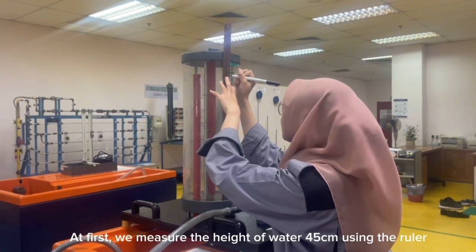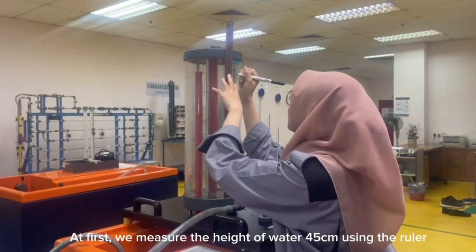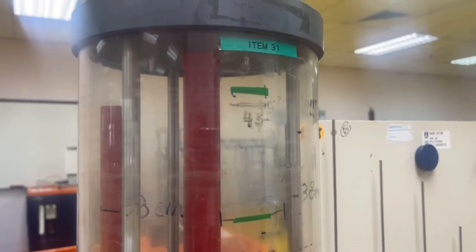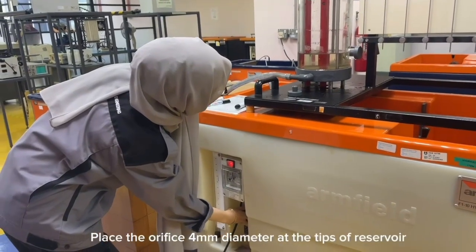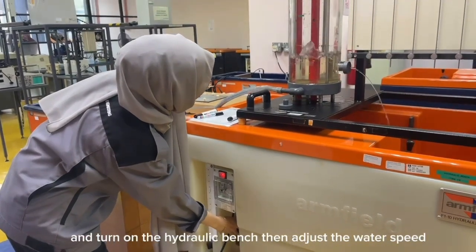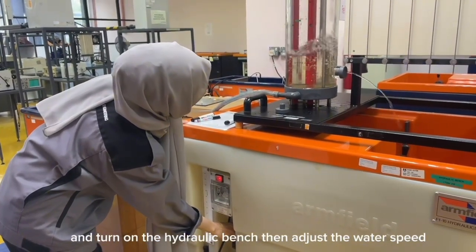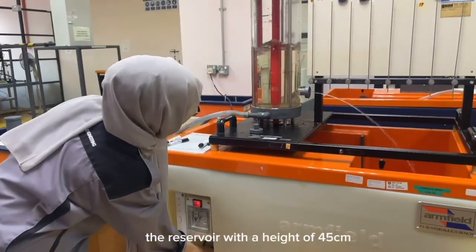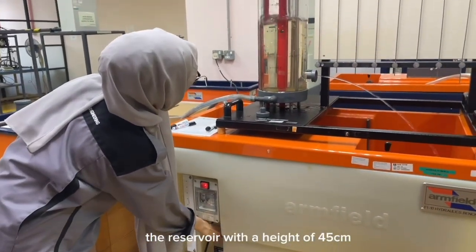At first, we measure the height of water, 45 cm, using the ruler. Next, place the orifice, 4 mm diameter, at the tip of the reservoir and turn on the hydraulic bench, then adjust the water speed and the adjustable overflow until the water fills the reservoir to a height of 45 cm.